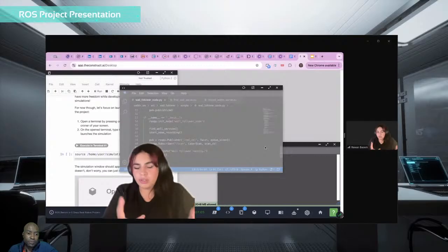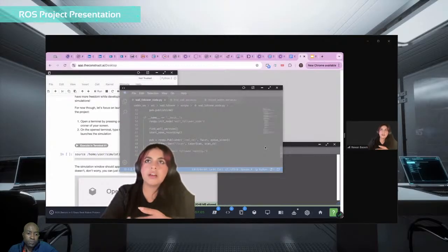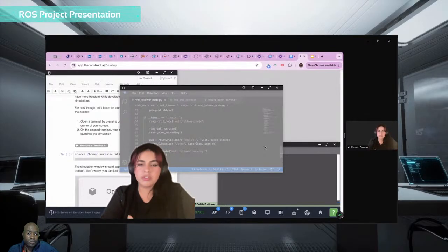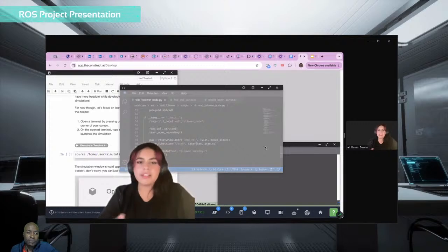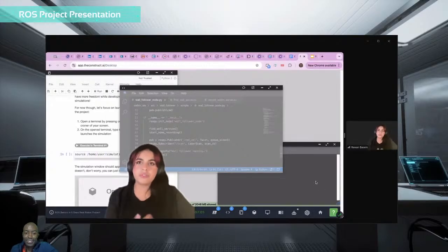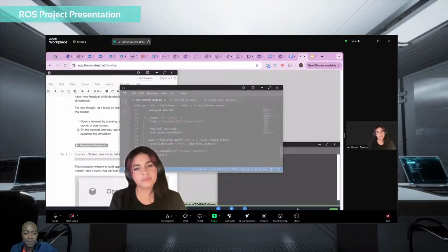It's short term, and actions are used for long continuous commands you would like to do, and it also has feedback and a result and cancel, which does not exist in topics and services. So that's why it's mostly used for long runs, like reading the geometry, getting the trajectory of the robot, and that's, I think, the most difference between them. Yes, those are the biggest differences.